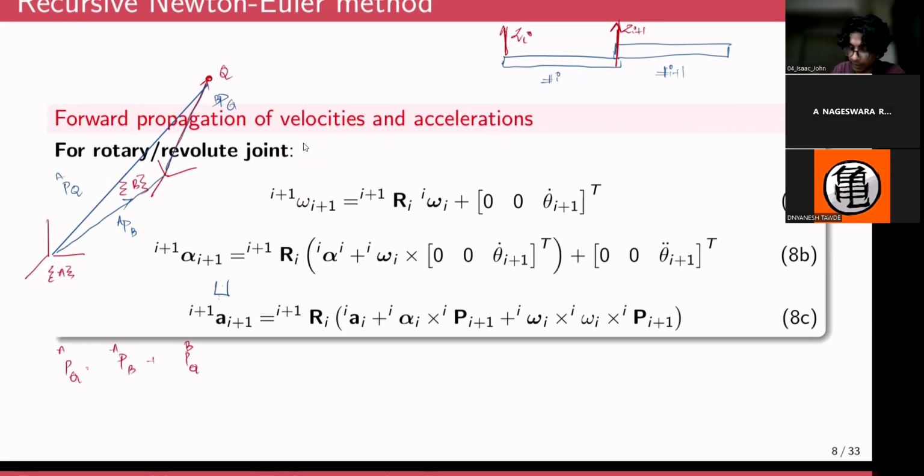But when we are expressing vector additions, everything will have to be brought into a single frame of reference. So this term and this term are already expressed with respect to the fixed frame of reference A, but the vector Q is represented with respect to the moving frame B. So to bring everything with respect to the fixed frame, we pre-multiply the vector with the correct rotation matrix, which is the rotation matrix of B with respect to A. Now every vector quantity is represented with respect to a single frame of reference.